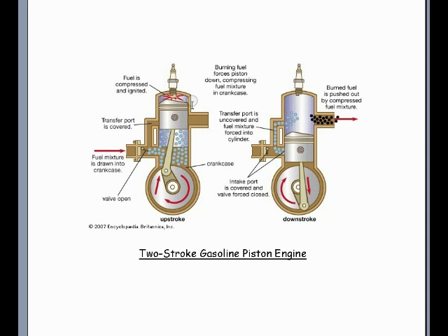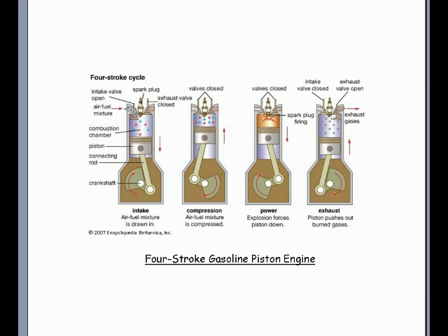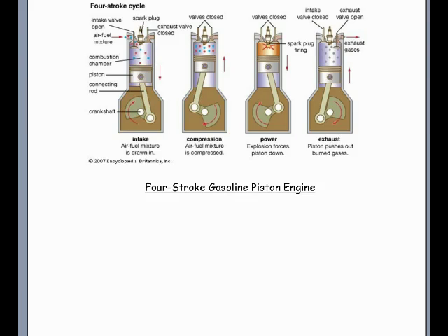You cannot use straight gasoline in a 2-stroke piston engine because the fuel itself lubricates the engine, and it is required to be mixed with 2-stroke oil before it is delivered into the fuel tank. There's no standing motor oil like there is on the 4-stroke gasoline piston engine.